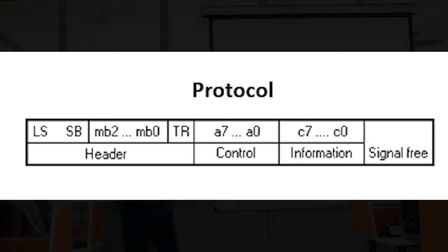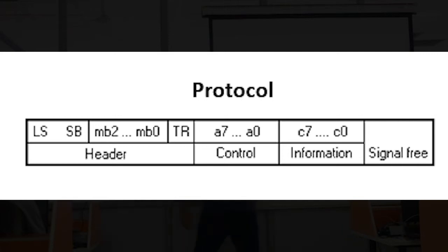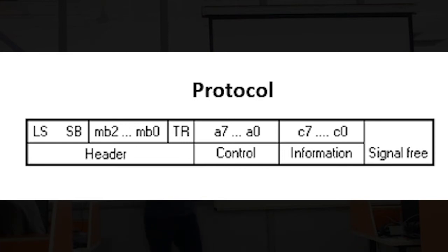TR is just a time which is given for the receiver to receive something. Like when the mode ends, TR is a cool-off sort of a period. So in that period, it lets the receiver know that the address bit is coming now after some time, just to calibrate that. Okay, and then there's a signal free time of 2.6 milliseconds. So you can't have 2 button presses within 2.6 milliseconds. You have to give at least 2.66 milliseconds between 2 button presses.